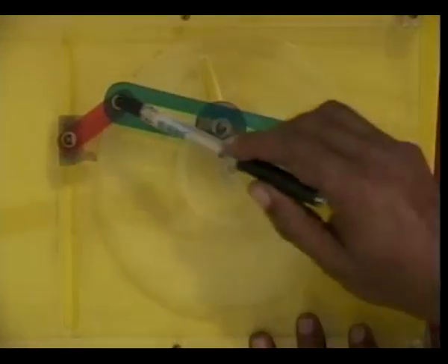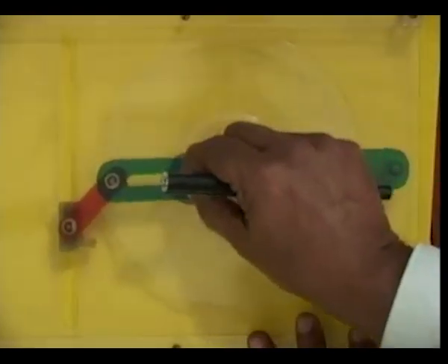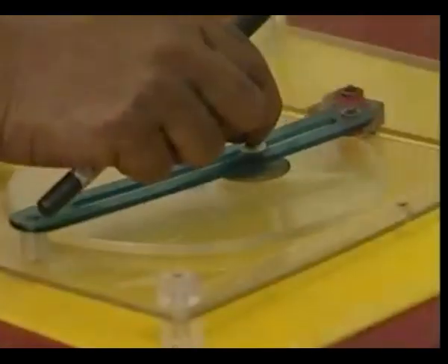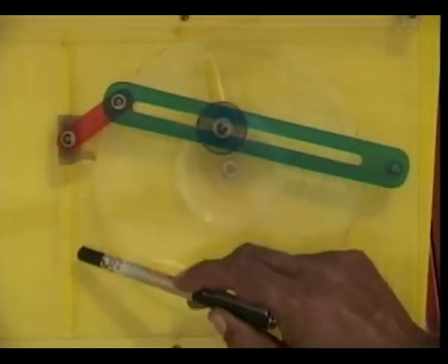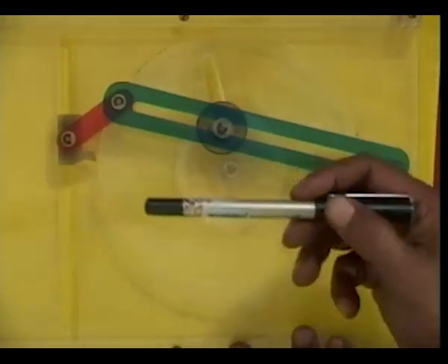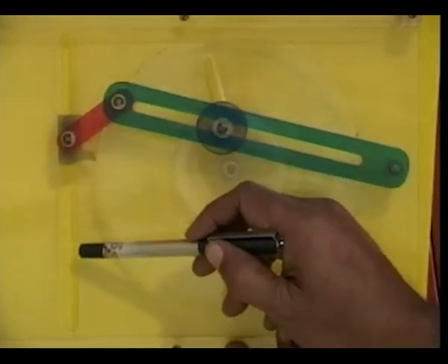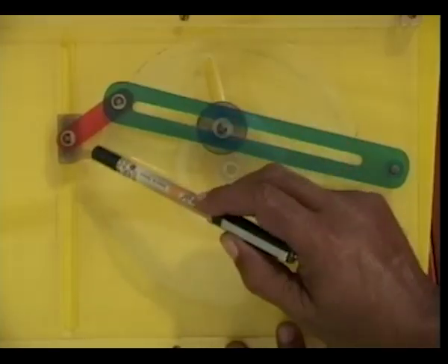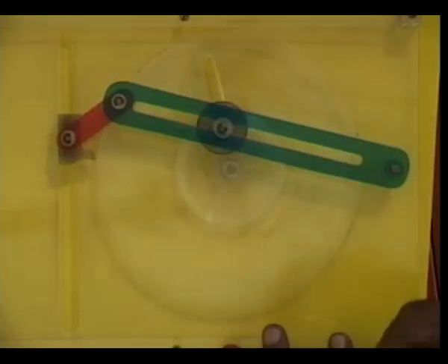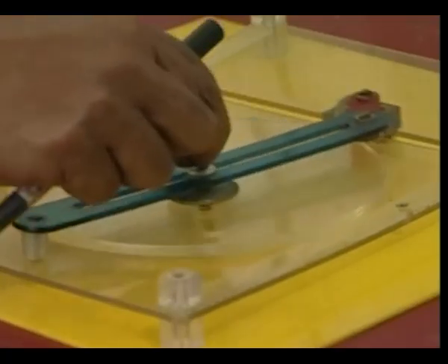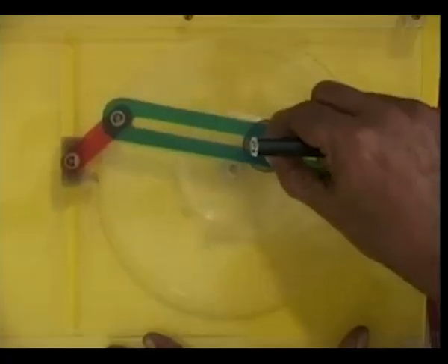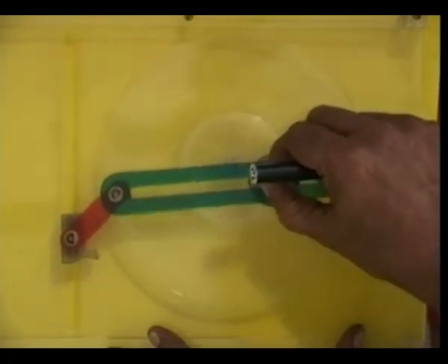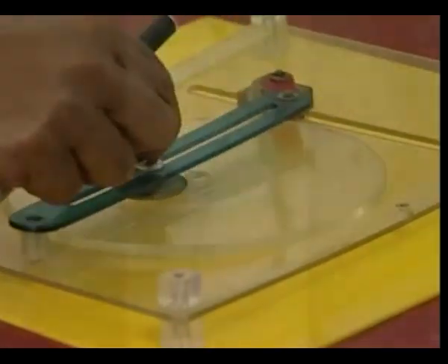So we have a 6-link mechanism here, where the continuous uniform rotation of the bull gear is converted into the to and fro motion of the cutting tool. Now, the cutting tool during the forward motion is doing useful work, and we have to maintain a proper cutting speed. However, during the return stroke of the tool, this is not doing any useful work, so I would like to make the return faster, and that is why it is called a quick return mechanism. As is seen very clearly, if I rotate the bull gear at almost uniform speed, the forward motion is slow, but the return is faster.